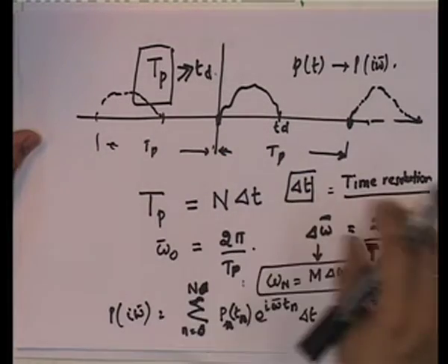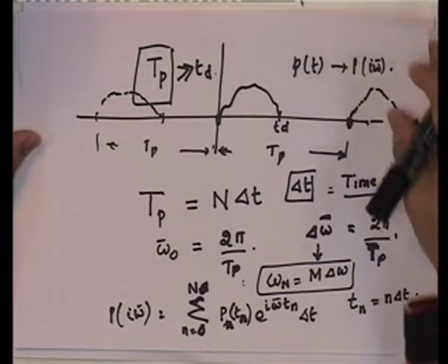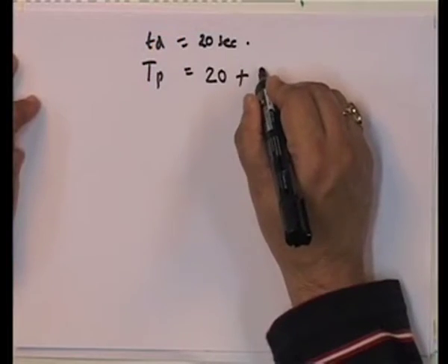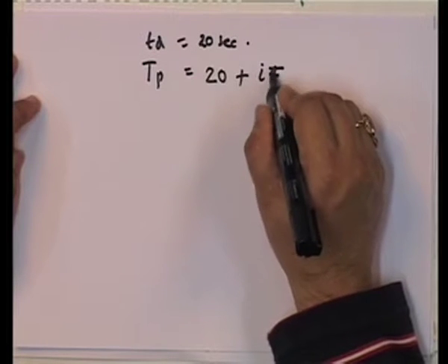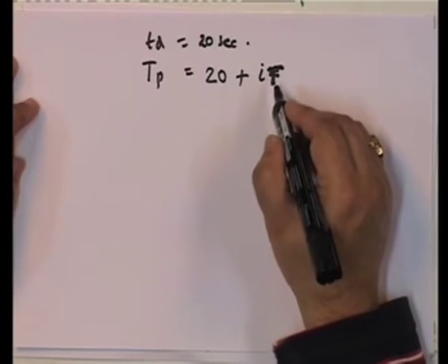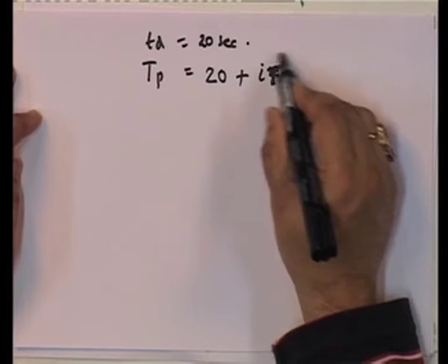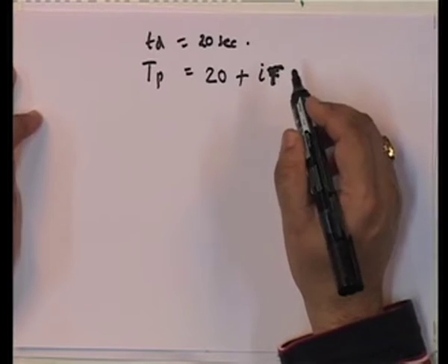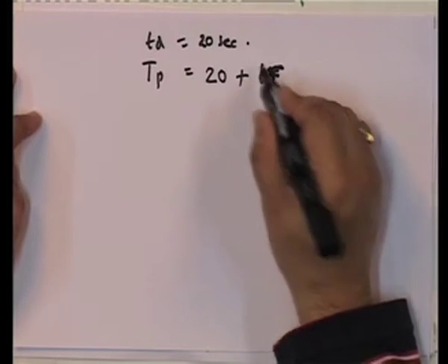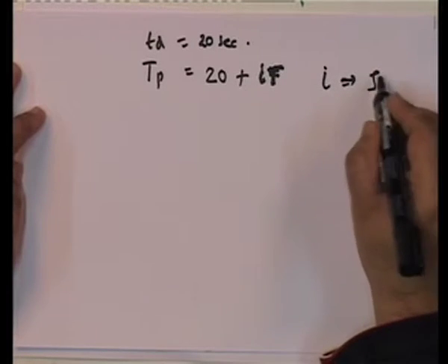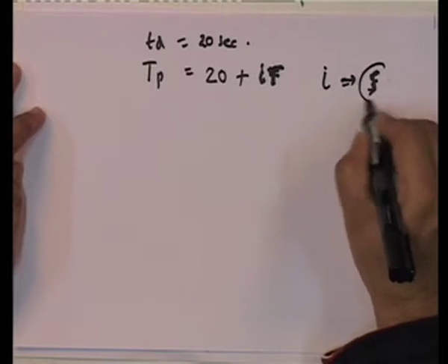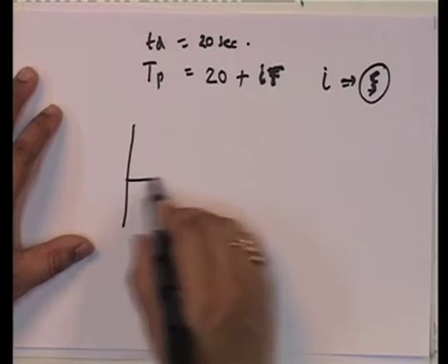Now, when you are taking this, it implies that this will give you certain aspects. So, if it is a single degree of freedom that you are looking at, I know that I will require some I times T, where T is the free vibration time period of the structure. And what does I depend on? On xi, because remember, this is free vibration.